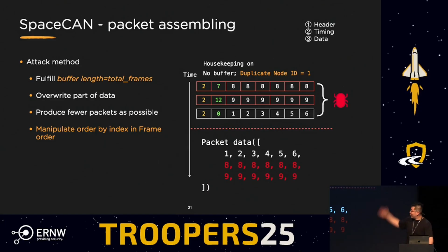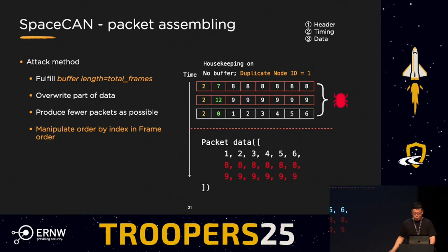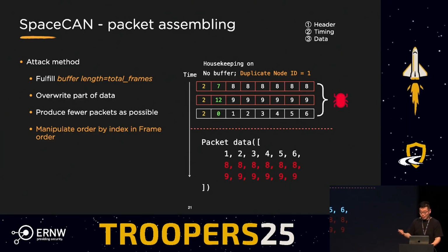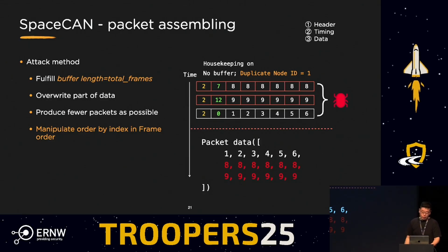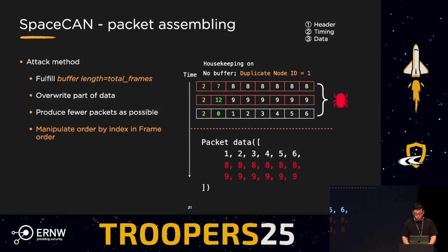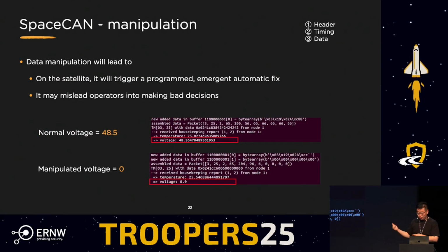So basically, you can do it like that. If you send 2 malicious frames at first, you will start to assemble in any order you want. So in this case, you will have 1 to 6, and depending on what order you want, you can just put random numbers in the second reserved byte, and you will change to the different order that you want. So that's how we can spoof this kind of internal communication.